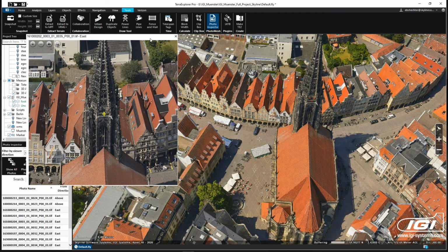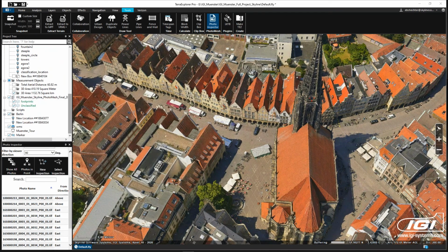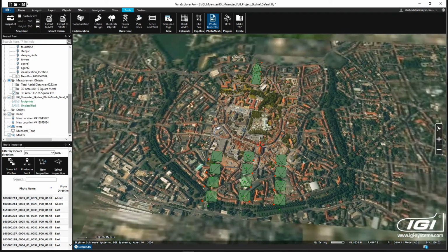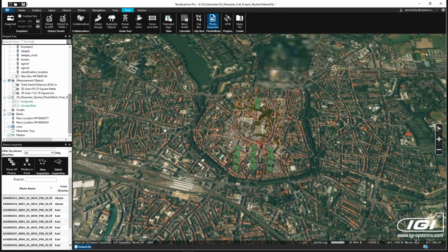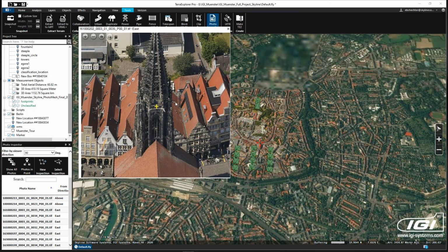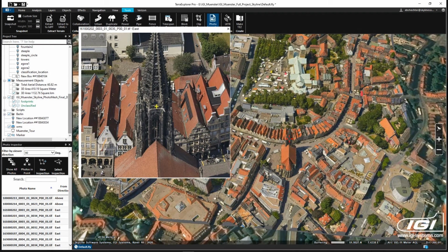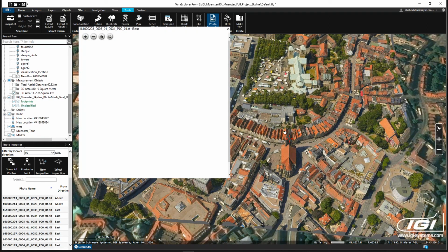So you produce the 3D data, and then you can load it into Terra Explorer. Terra Explorer is our desktop application. We also have the web application for it that I will jump into. So we can see over here, we have the ability to visualize the images. This is the photo inspector, so I can click on a spot and then load the image and the different images that were used to map the 3D model in that area and move between them.